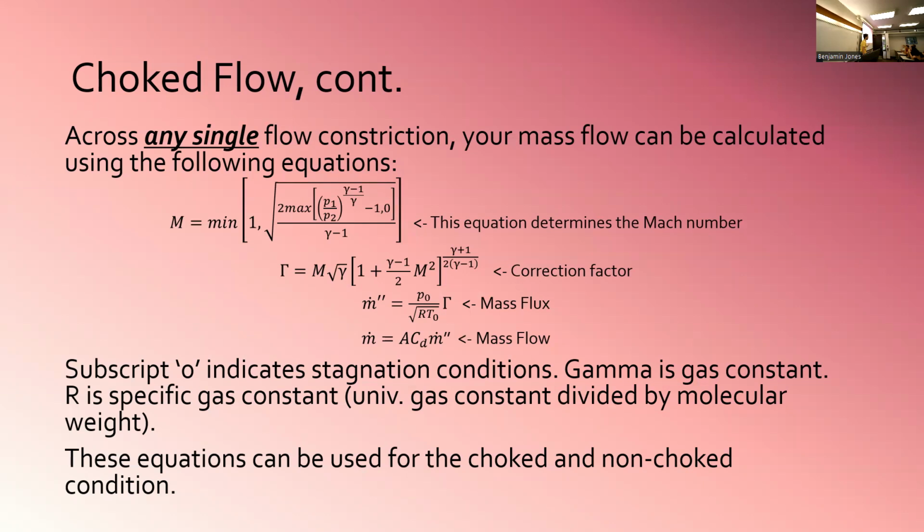And with this equation, it can become evident why an increase in upstream pressure causes an increase in mass flow, while a decrease in downstream pressure does not cause an increase in mass flow. All that pressure 2 is ever used for is checking if the flow is sonic. I should change that to P1, but whatever. This is P1. I will change that and then re-upload the PowerPoint.